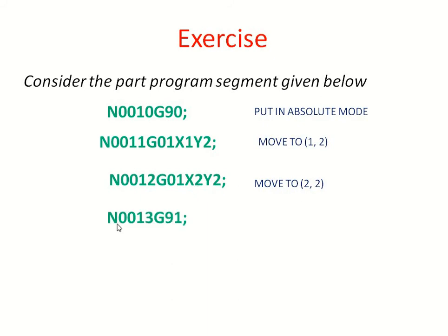Similarly, the next block N0013 G91 represents the incremental mode. With incremental mode we can move to the next position.